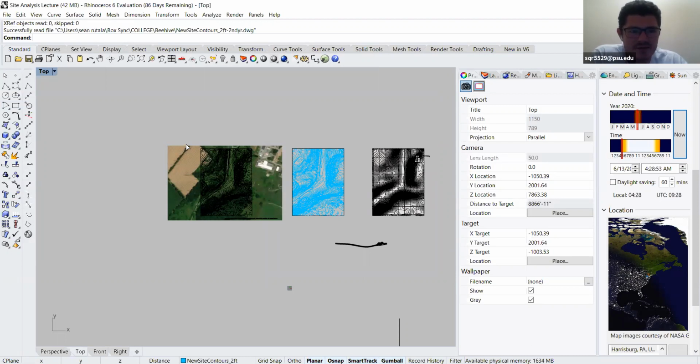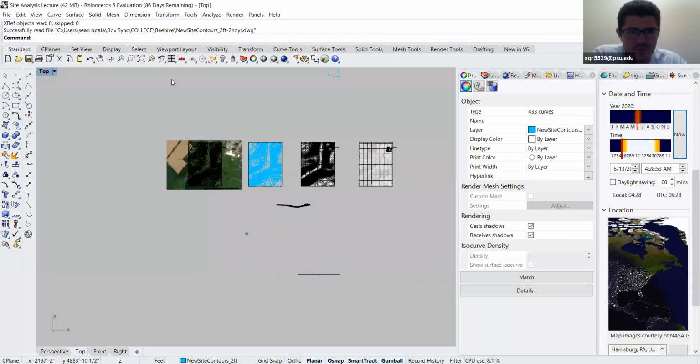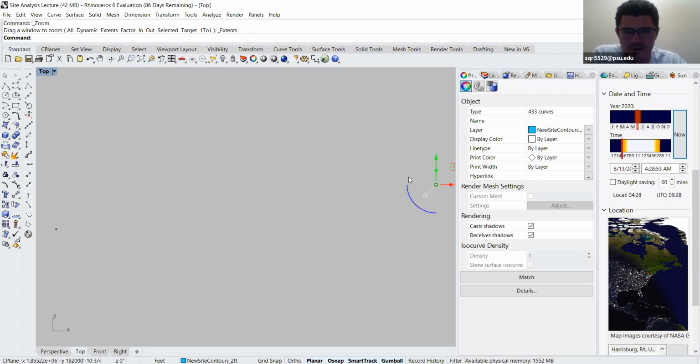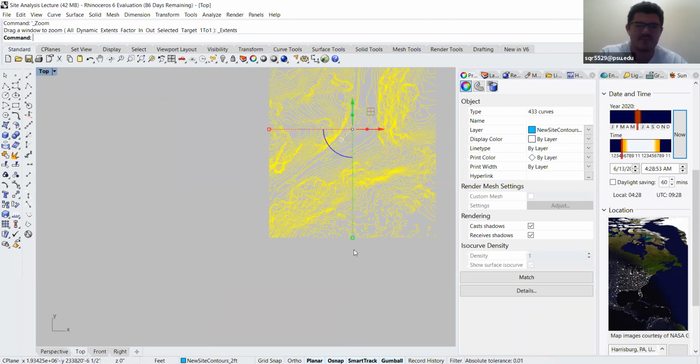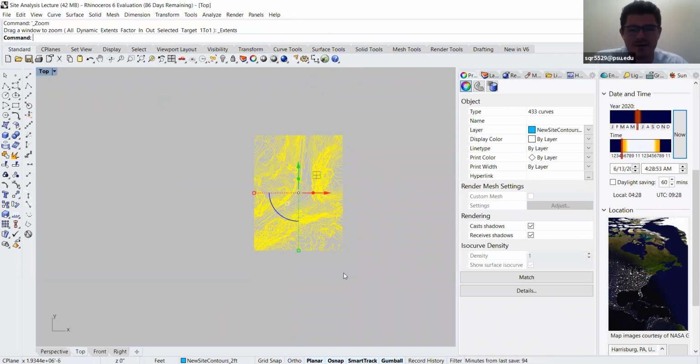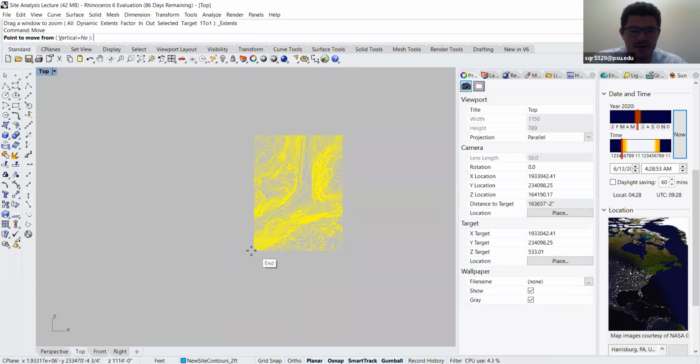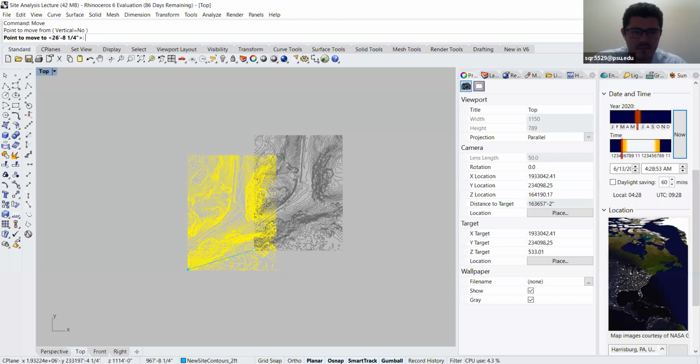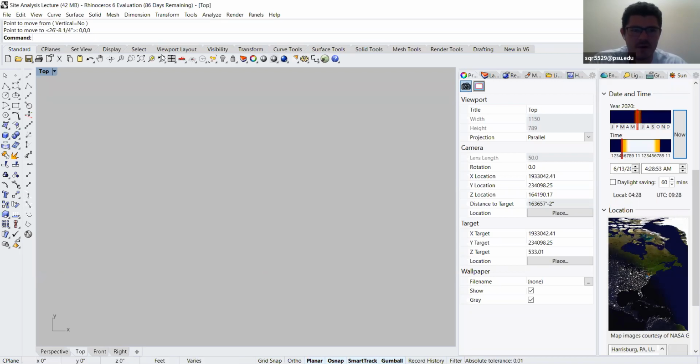One thing that is weird in Rhino is it likes to send drawings into their space referenced to AutoCAD. If you click zoom out, I'm working over here, but you can see that the drawing I just imported is all the way over here. So just be cautious about that when you bring it in. Don't think it's just not there and import it a couple times. Then you can just move it back to where you were working.